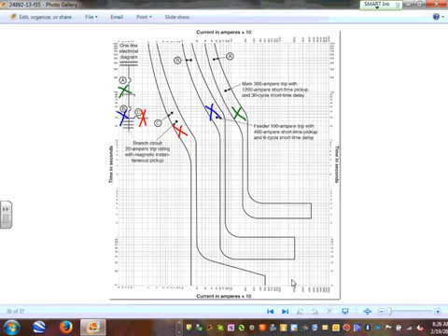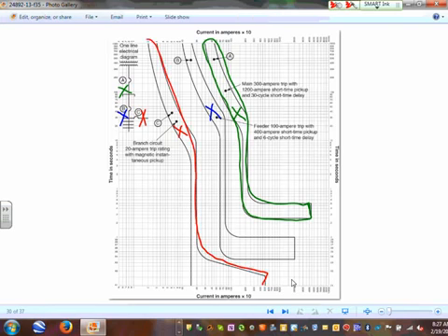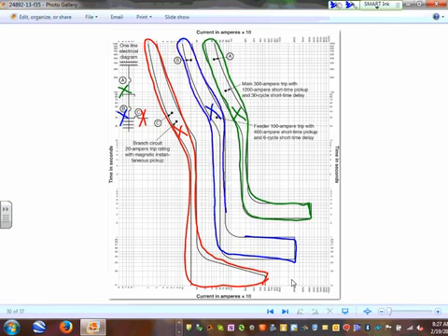I want you guys to know that when we go to SKM and coordinate between the curves, that's what I'm looking for you to do. They're not going to touch in any way, shape, or form. Can you guys see that? Meaning they're adjusted time-wise and pickup-wise. So this circuit breaker, no touching whatsoever. This means fully coordinated with this circuit breaker at the bottom here. You see that all the way, no touching. And the last one is this one here, which comes all the way. That's what they call a fully coordinated system.